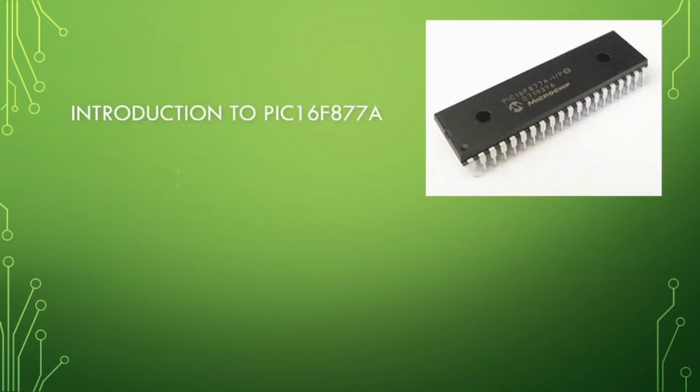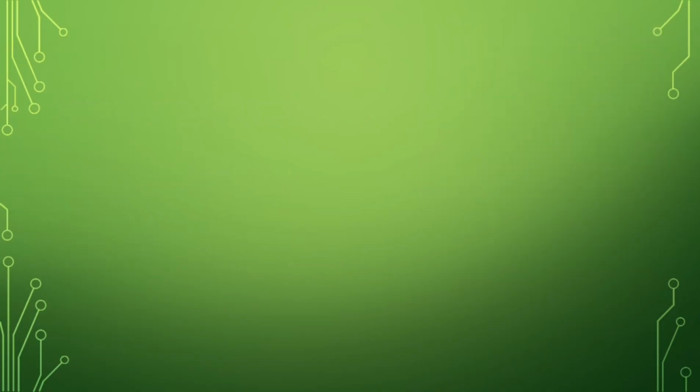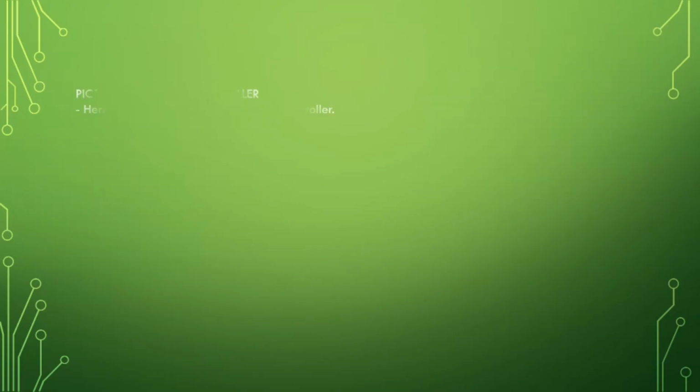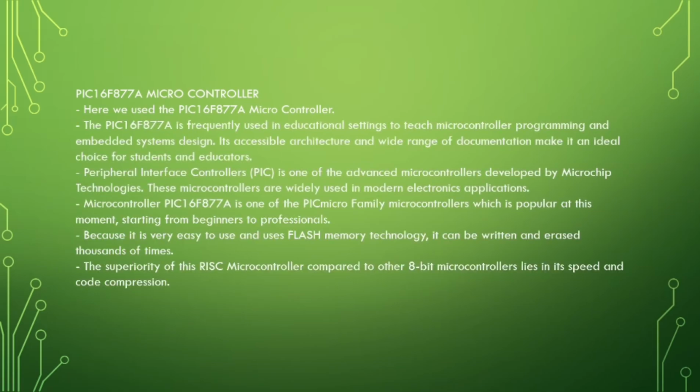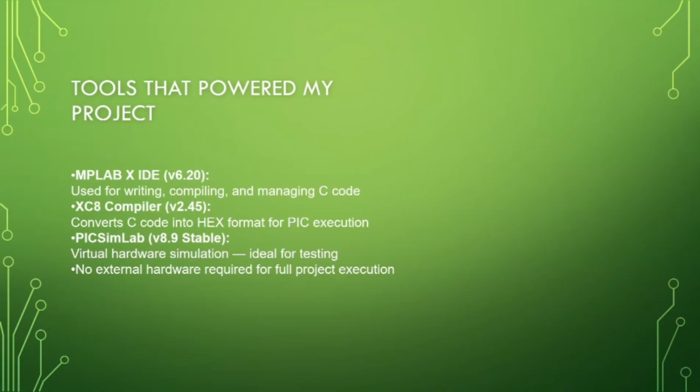Introduction to PIC16F877A. It's an 8-bit RISC microcontroller from Microchip, operates at 20 megahertz with 35 instructions. Features are SRAM of 368 bytes, EEPROM of 256 bytes, and for digital input output, 5 ports A to E, ideal for simulation due to simplicity and flexibility. Here is additional information about the PIC board. Tools that powered my projects are MPLAB X IDE, XC8 compiler, and PIC board.